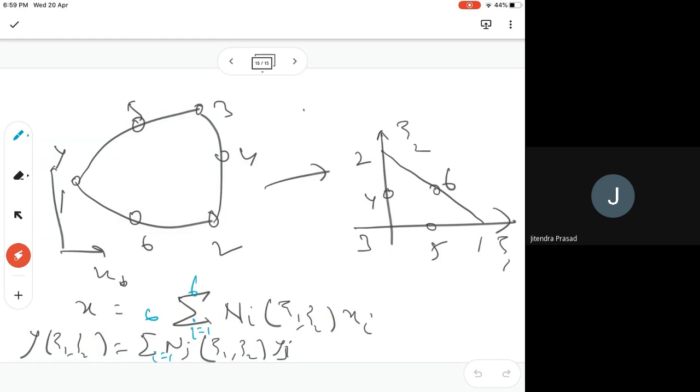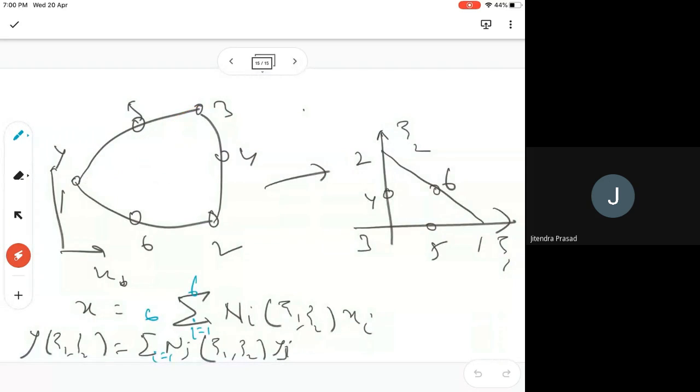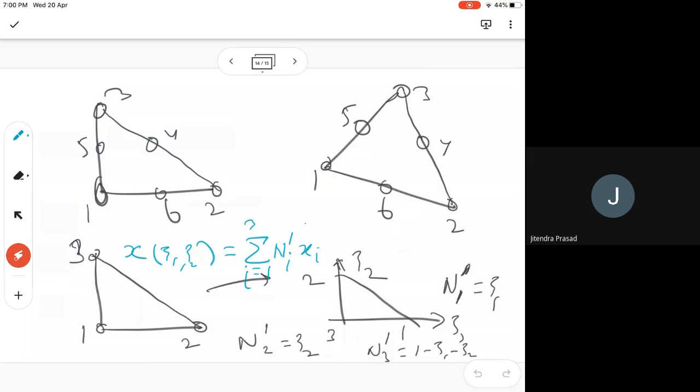Yeah. So this is also correct. You can also do it this way, but the general formulation is for general purpose. For example, if it is a straight line but your node is not exactly in the middle, then in that case you have to use the general one. Whereas this can be used when all the edges or sides are straight lines and the middle node is exactly in the middle. Then you can define this based on just three nodes only.